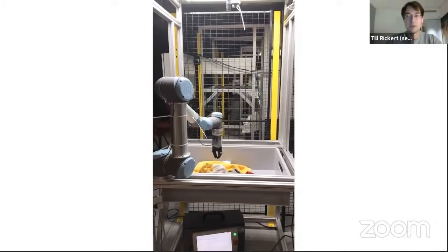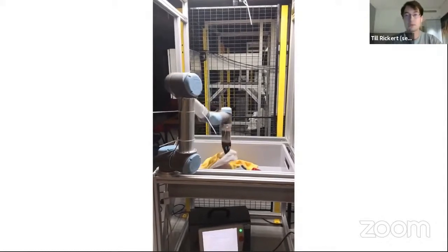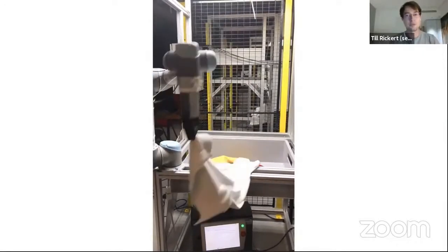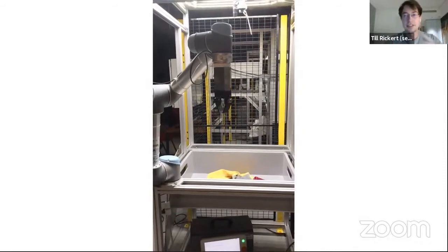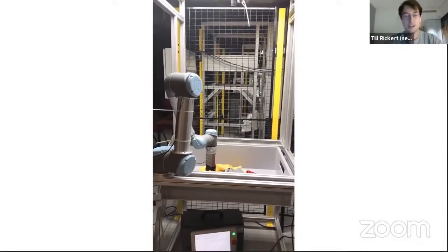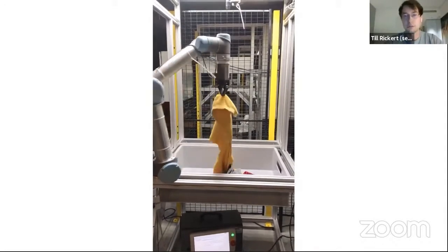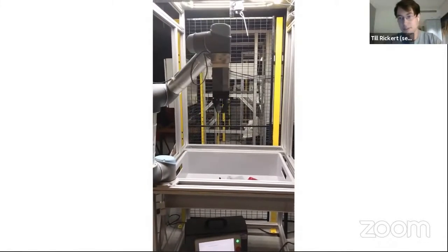And here we use our same computer vision. We extract seams of the towel, and we assess where we can grip something so that in the end we receive one single towel. The complete process is implemented with off-the-shelf hardware components: a Universal Robot in this case, a normal gripper, and only the gripping fingers we designed ourselves. In this case, they are 3D printed.